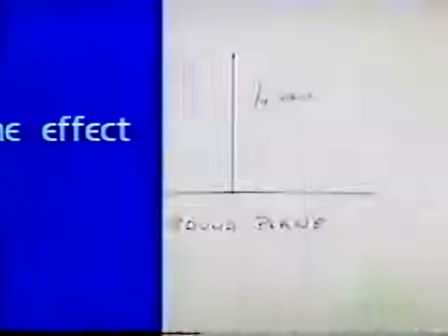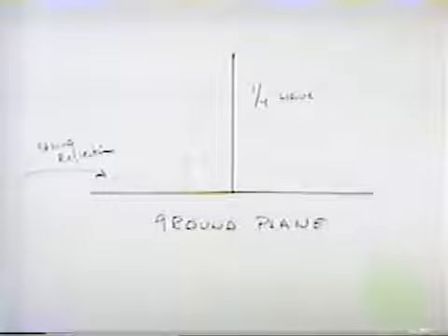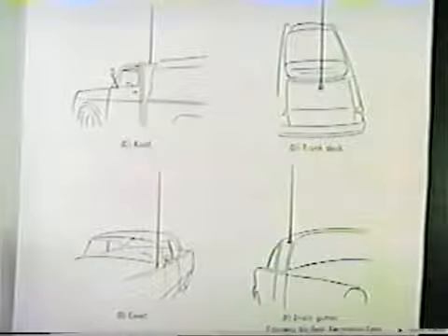I just want to point something out when it comes to this type of antenna. A quarter wavelength antenna of itself is not a resonant length antenna. In order for it to be a resonant length antenna and to accept the power and radiate it, the power that you have available in the car or whatever, this antenna has to look like a resonant antenna. And the resonant antenna means that it should have a ground plane effect. And in the case of your car, of course, you're putting it on the roof of your car, which is metal, and that creates the ground plane effect.